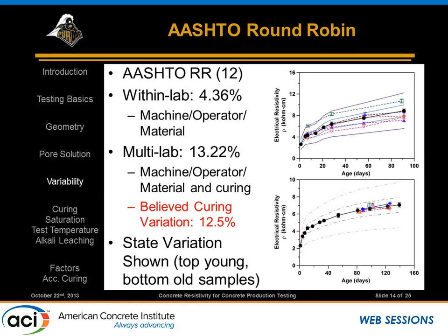And what you will notice here, this variability is much higher than when we took the mature samples that had all been conditioned together. This implies that the conditioning is incredibly important in these samples, and paying attention to the moisture, paying attention to the temperature, paying attention to the humidity is very, very important because that has a big impact on the results of this test.